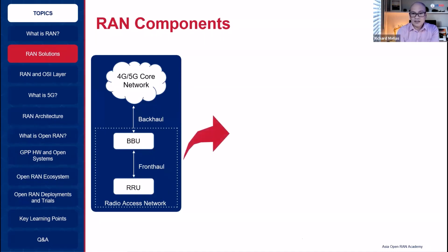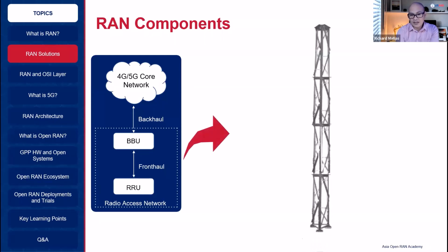So when you look at the components physically, this is how it looks like. Typically, we need to have a tower structure to elevate yung ating antenna system. As you can see in our previous simulation, typical in an urban area, we will have around 15 to 20 meters yung antenna height natin. And then for suburban areas, we'll have 30 meters.